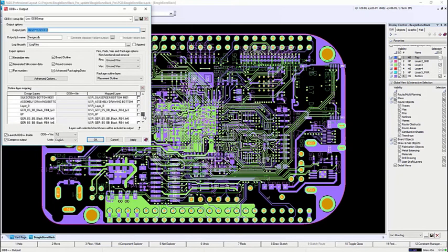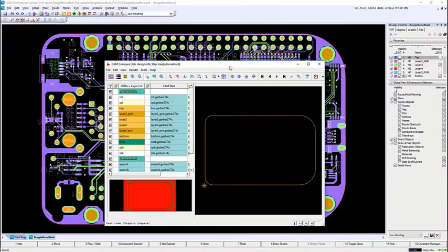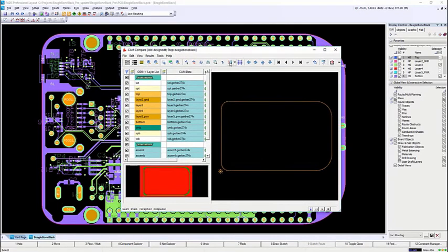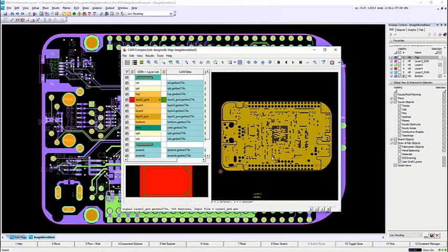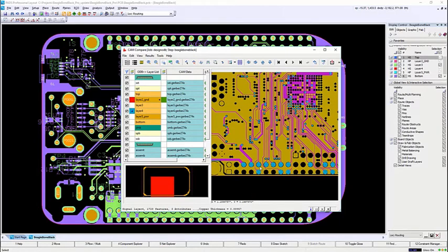In the ODB++ output generation window, you can once again select what information is created. Easily select different options to export, such as silkscreen information, outlines, nets, and packaging data. Then, select layer information to include in the output file and map user layer data to one or multiple layers. By selecting Launch ODB++ inside, the software performs several steps to compare the generated ODB++ output with equivalent reference files to identify variances.